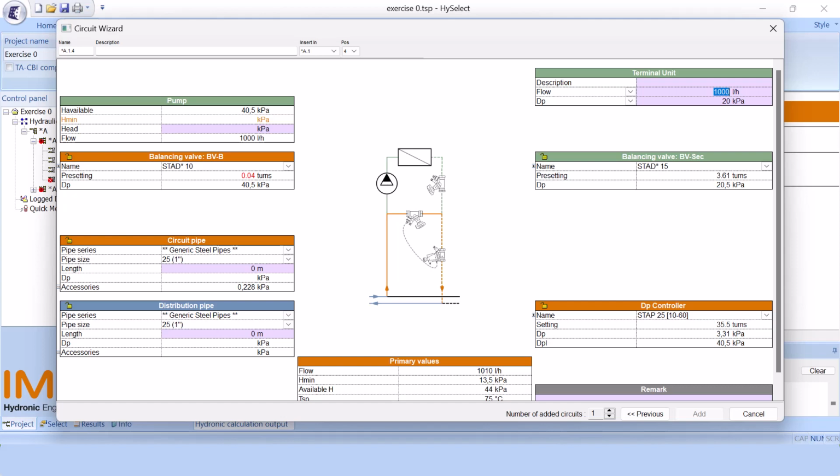When there is already enough differential pressure from primary, this case remains empty and a remark pops up. When the needed pump head is higher, H min is added. This H min is the setting from the technical parameters section. Complete the head when already known. The balancing valve and the bypass will always be a small one to deliver the differential pressure to the secondary. The dP controller is selected to deliver the constant dP for the circuit.